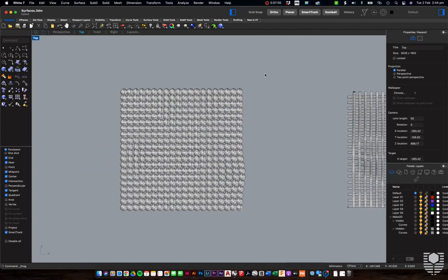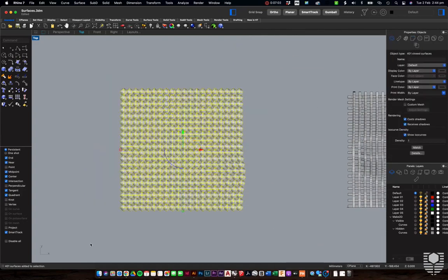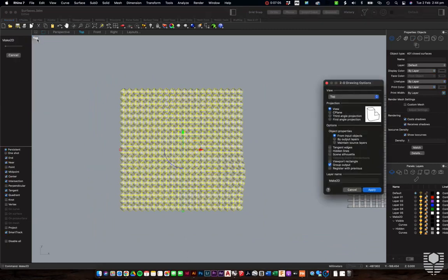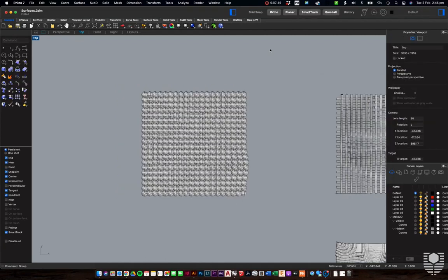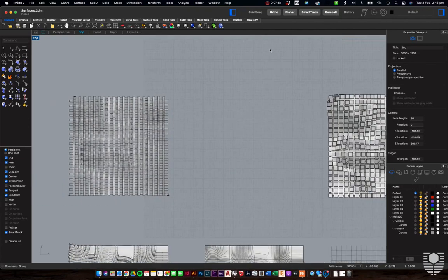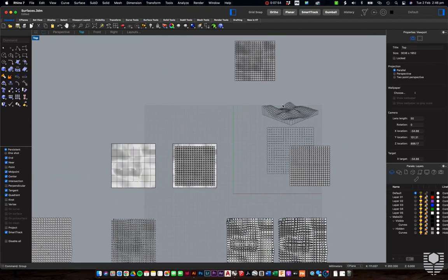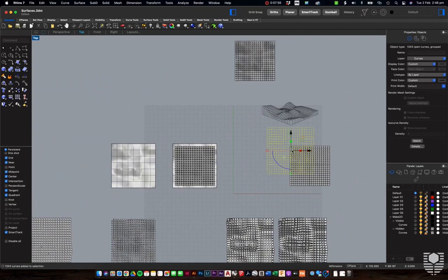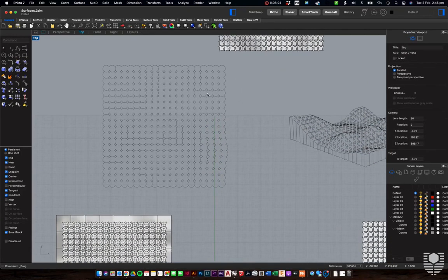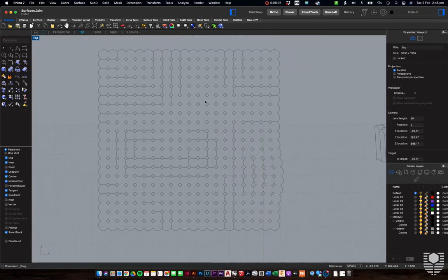just to make things a little bit easier for us. Zoom down to it, select everything we want, make 2D, and this time we're in the top view, so we're looking directly down onto it. Hidden lines, we don't want to see any of that stuff, just the view, and just group the output. I click apply. Again, don't click anywhere while it's done. You just want to type in group, and then you'll be able to scan over to where it is. And I have it over here grouped together. And I can just move it to where I would need it. And I've got a plan view looking down over the top.